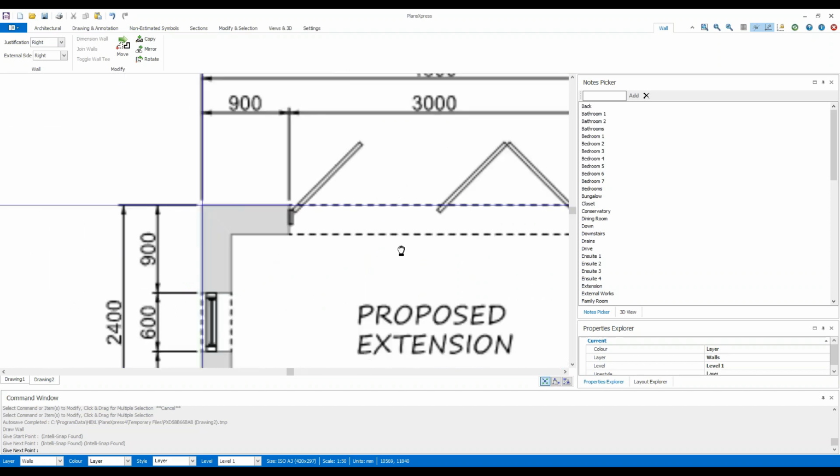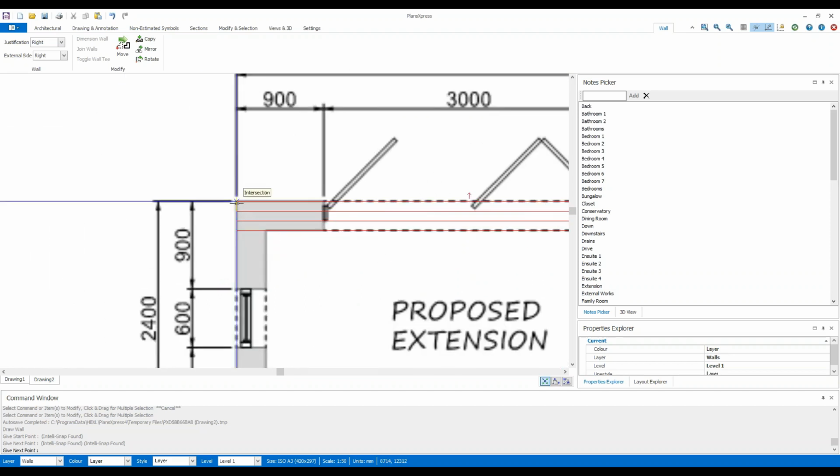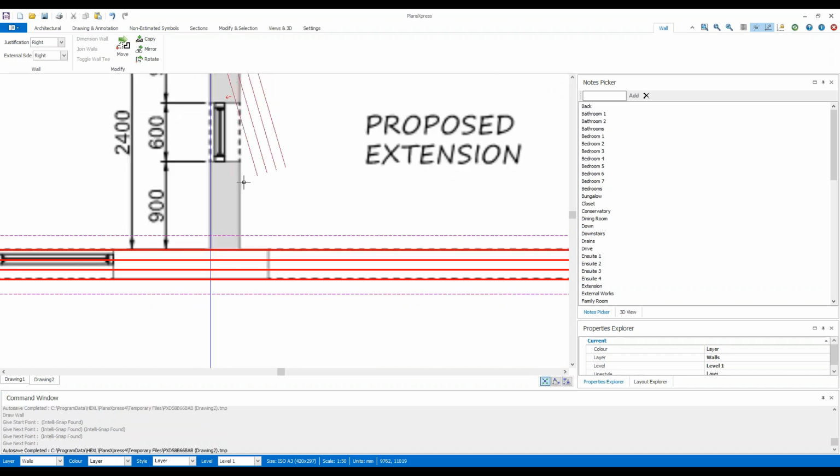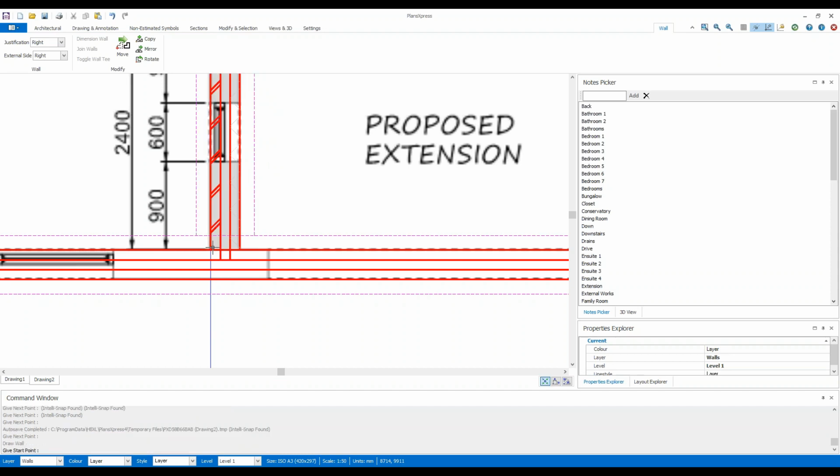Hold down the scroll wheel, drag your drawing page over, and continue working your way around the extension, clicking on each intersection or perpendicular point at the corners of the extension. Continue in this way then to finish drawing our horseshoe shape. And then you need to press the escape key on your keyboard.